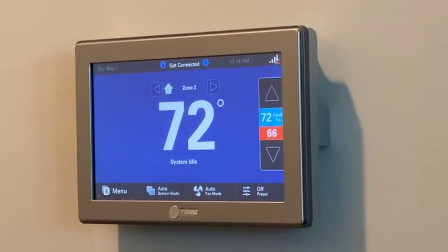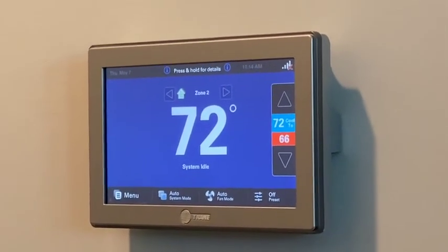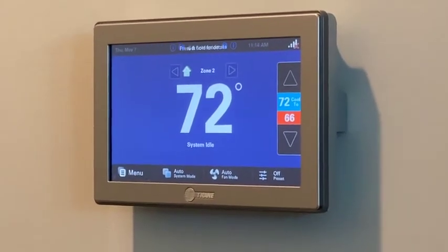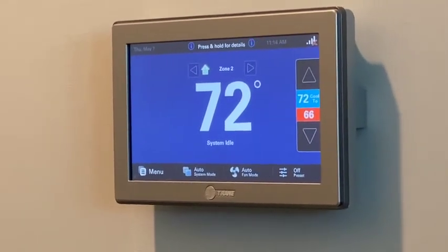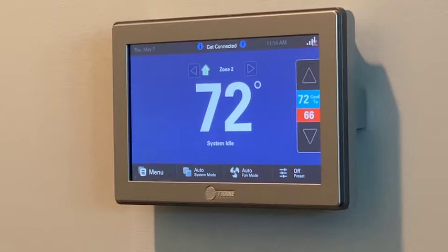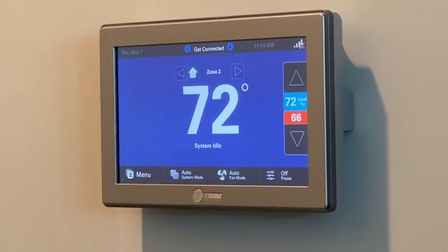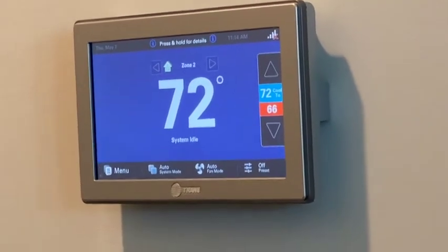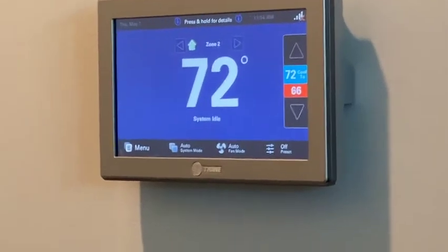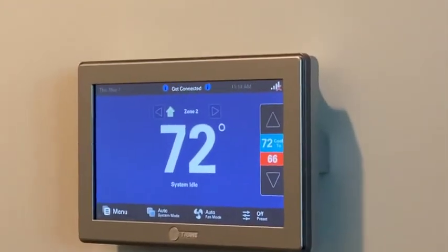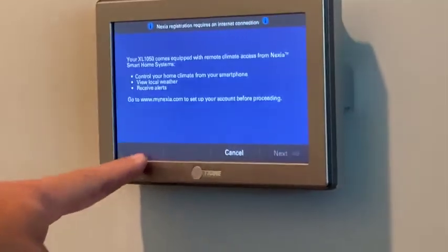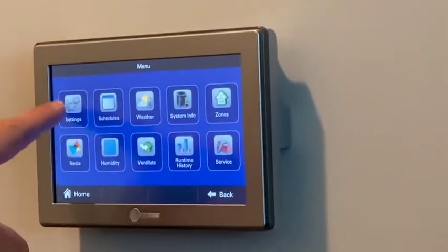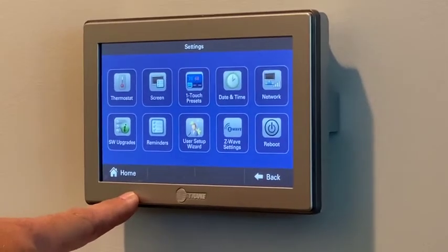Because that's what you had? You had a Nest? I never wanted to install them, and a friend of mine got one. I was being nice to a friend of mine and put it in, and it ended up that the Nest thermostat was bringing the compressor on in the middle of the night, because the Nest thinks that it learns you. So it was thinking, okay, it needs to do this for whatever reason, and it was bringing the compressor on to run the electric bill up.